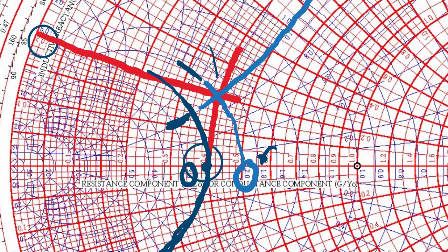You can see it's between 3 and 2. And then for the reactance, if we convert that independently to a susceptance, we're just going to follow this curve. The inverse of 0.2 is 5.0, and again the top half of the chart is negative. So let me continue this circle around.